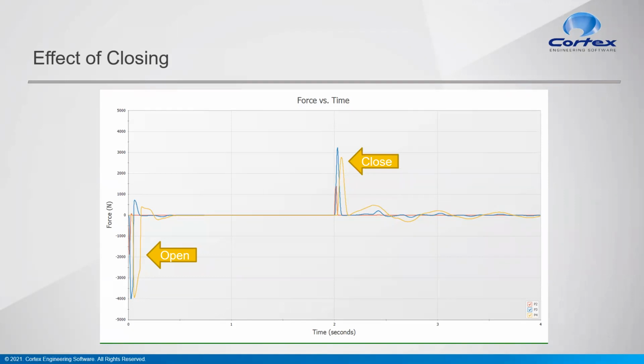If you see here, there's some slight differences in the force curves that we've generated. For one thing, as the valve opens, we have a really flat section within a few hundred milliseconds after the valve opening, whereas when we have a closed system, we get a bit of a ringing. In other words, we get the mass flow or the forces oscillating in the piping system.